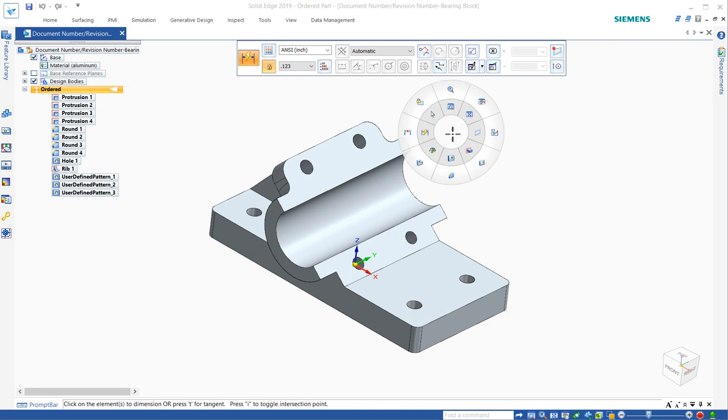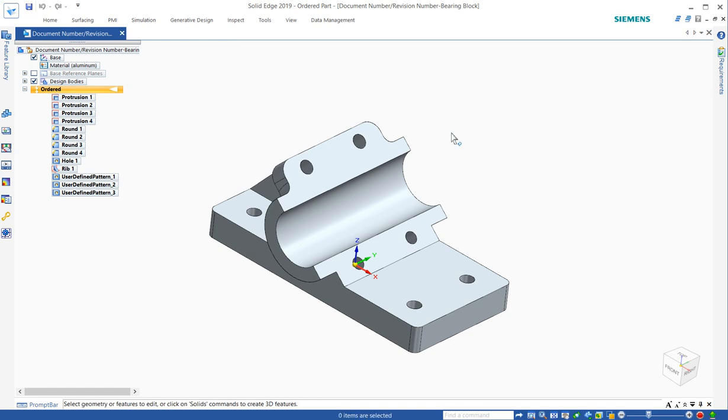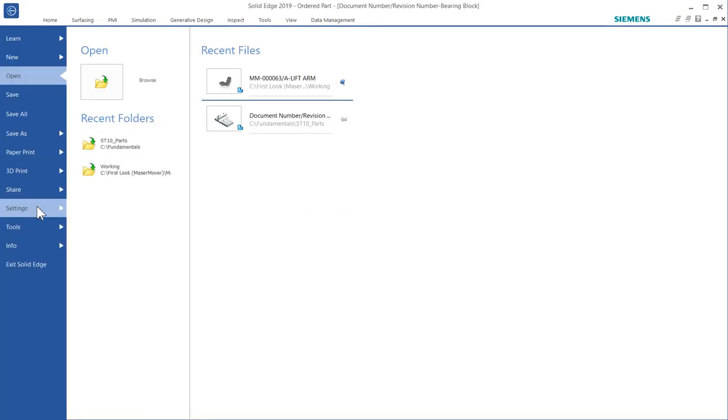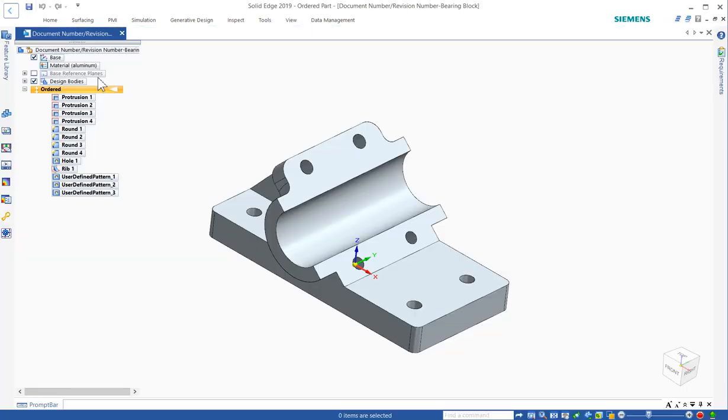And there's also a timing which you really may want to adjust. It's the number of milliseconds that I have to hold the right mouse down. If I right click briskly, I get the context menu, but if I right click and hold for a number of milliseconds, the radial menu pops up. So that's a setting, and it's set to a kind of high value out of the box.